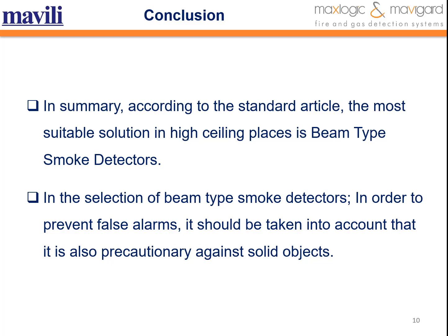If a solid object enters between the receiver and transmitter momentarily, after a certain delay time between 6 to 8 seconds, if the interruption of the beam exchange continues, the detector should go into fault state. If the detector goes into fire state due to a solid object, a false alarm condition may occur. For this reason, this feature should be taken into account when choosing a beam type smoke detector.